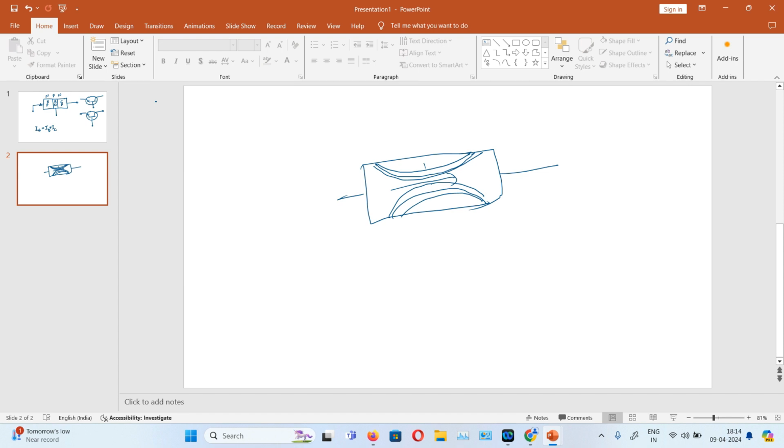How this region is growing is actually controlled by potential. Since there is no current flow, the potential difference across the gate and the source drain channel is increased, and that's why it is getting controlled. So what is controlling the current flow? The current flow is controlled by potential difference. So the FET, or field effect transistor, can be considered as a voltage control device.